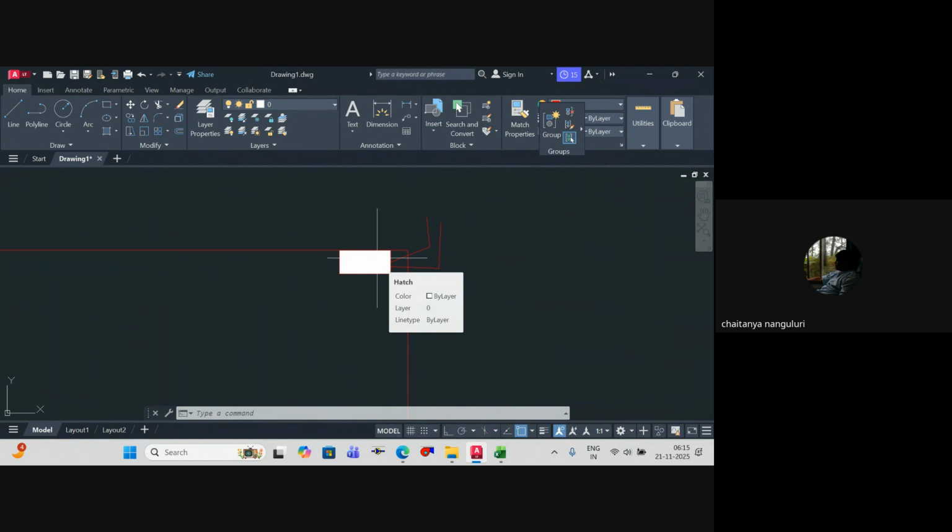No, sir. It is your only escape route, and you're closing it. So as per norms, you should keep it unlocked. But at the same time, obviously, you don't want to give any unauthorized access. You will be using the door only in case of fire, else you will not use that particular door at all. So if you keep it with your door positioning sensor, if someone opens it, the entire building will know that there's a fire inside the building.